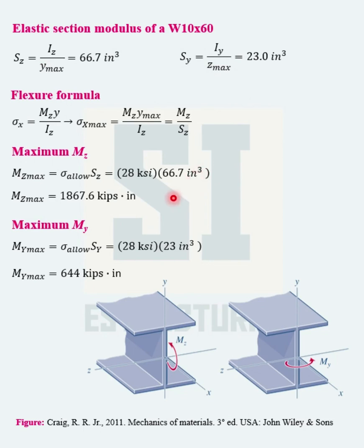However, the section properties of standard rolled structural steel shapes, such as the wide flange sections, including the elastic section modulus, are already given in tables for practical use. That is how the elastic section modulus were obtained in this exercise.